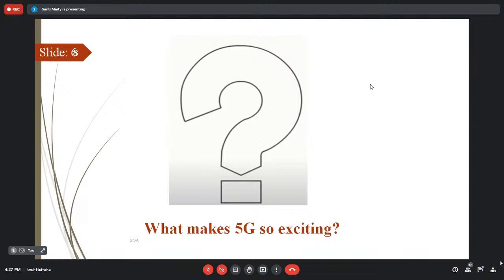The second thing coming into the situation is MIMO, multiple input multiple output. So the tiny mobile devices will be equipped with multiple antennas, and that will provide spatial diversity, multiple independent channels. So your signal has multiple copies, and at the receiver you can combine them to have a good signal. So this is diversity, or you can think of it as spatial multiplexing. So MIMO is another component that adds here.